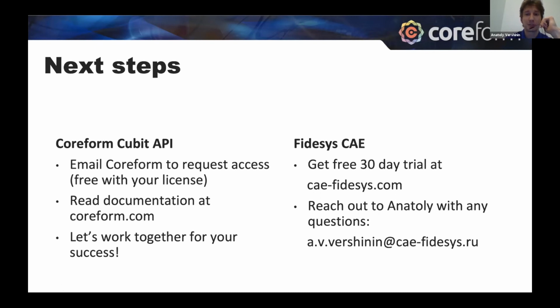It is based on Python. As I mentioned, the fidesis preprocessor and postprocessor are completely compliant with this Cubit Python API. So any end user could write scripts in Python and run them inside fidesis to do automation, customization, and scripting for fidesis using the API.